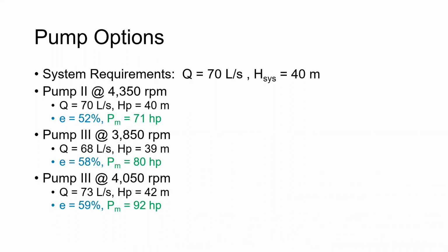So here's the summary of that. And I can multiply these out and figure out then what energy requirement is going to be the most. And if you want to do those calculations real quick, maybe tell me what you think the biggest or the least power consumption will be under these different operating conditions. So the efficiency is interesting, but ultimately we're looking at the power input, because that's going to tell us how much power the pump's going to require.